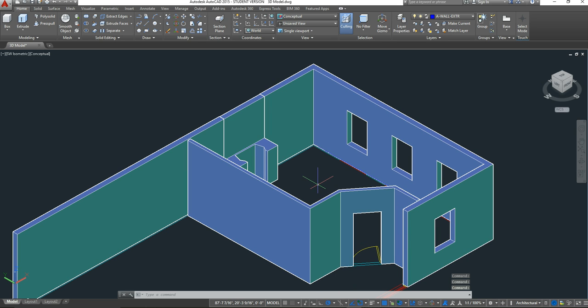So what I want you guys to do, again, for your final project, get your walls in place for your area that you selected to do. Also get your window openings in and also your door openings as well. And so this is how you guys would do it. This is how we would start any model that you're doing in AutoCAD. And so I look forward to talking more about this model in class on Thursday. Thank you.